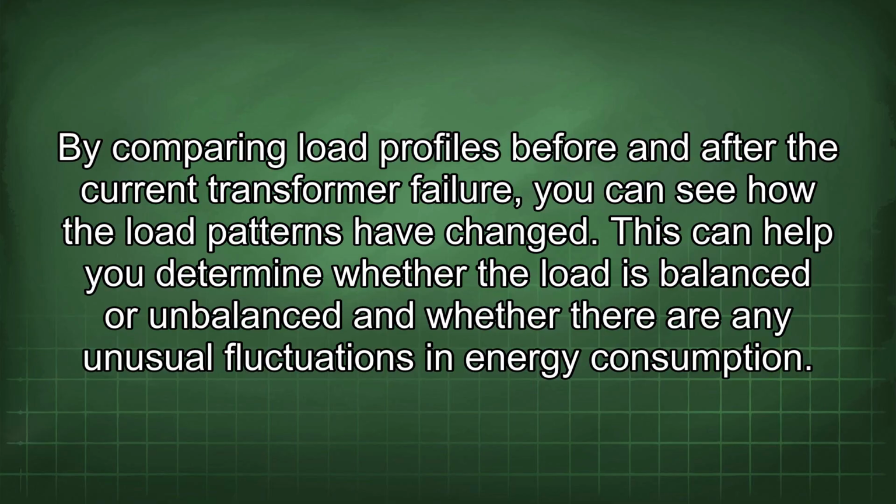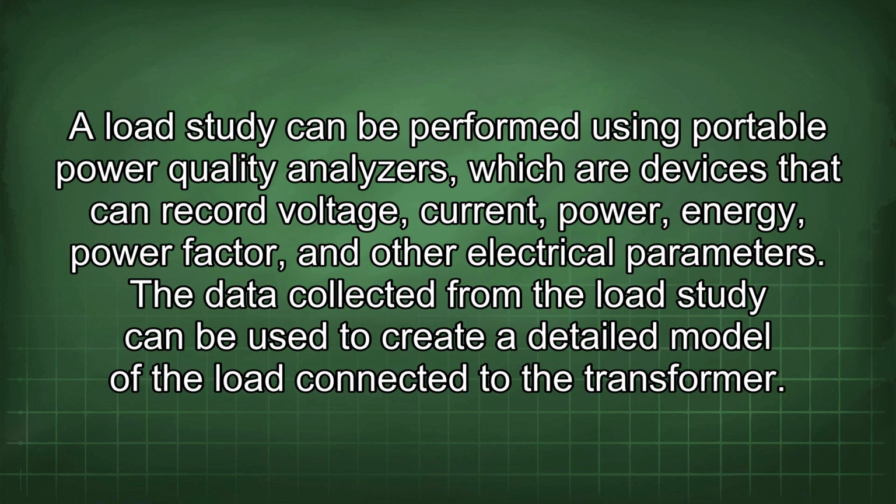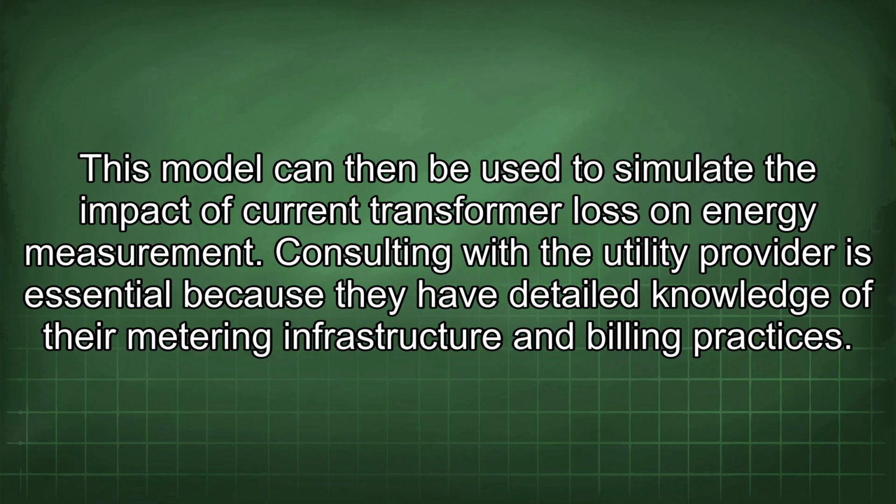Conducting a load study involves measuring the current and voltage on each phase of the transformer over a period of time. This data can be used to calculate the power and energy consumption on each phase and to determine the load balance and power factor. A load study can be performed using portable power quality analyzers, which are devices that can record voltage, current, power, energy, power factor, and other electrical parameters. The data collected from the load study can be used to create a detailed model of the load connected to the transformer. This model can then be used to simulate the impact of current transformer loss on energy measurement.